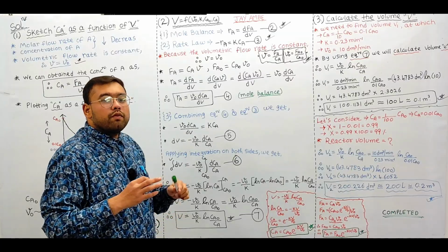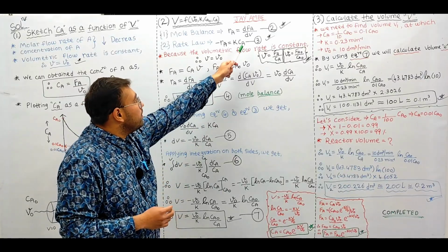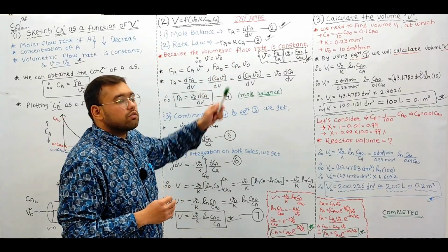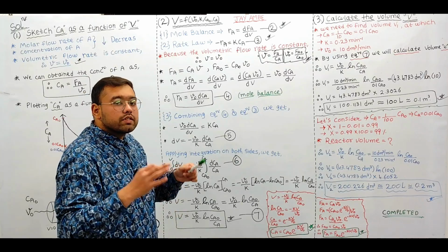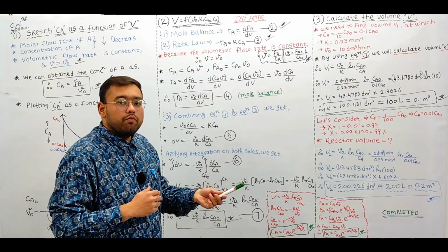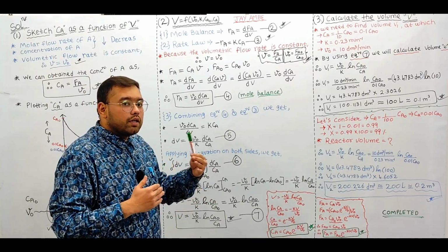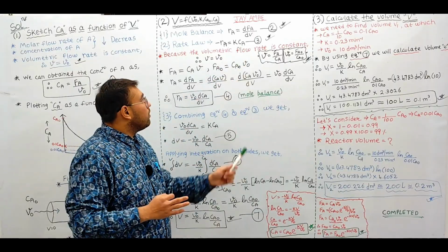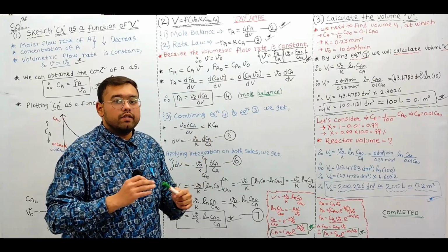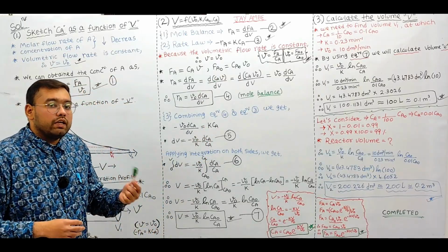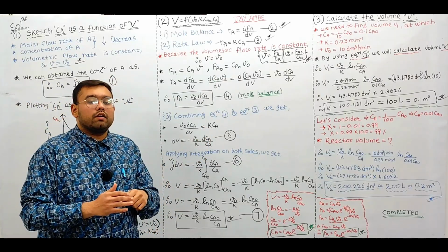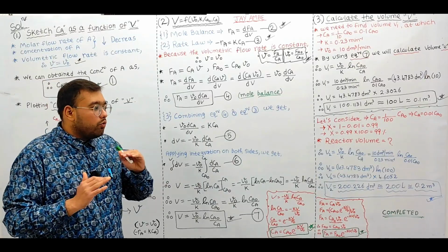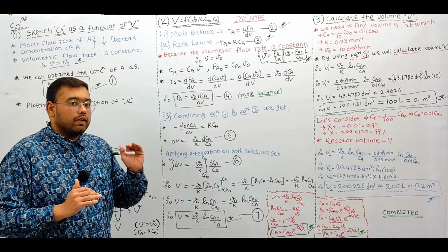If we have a higher concentration of reactants present in the reaction environment of the plug flow reactor, we will have higher rates of reaction. As the concentration of reactant decreases with the progress of the reaction, the rate will also decrease with respect to the volume of the plug flow reactor, in the axial direction.